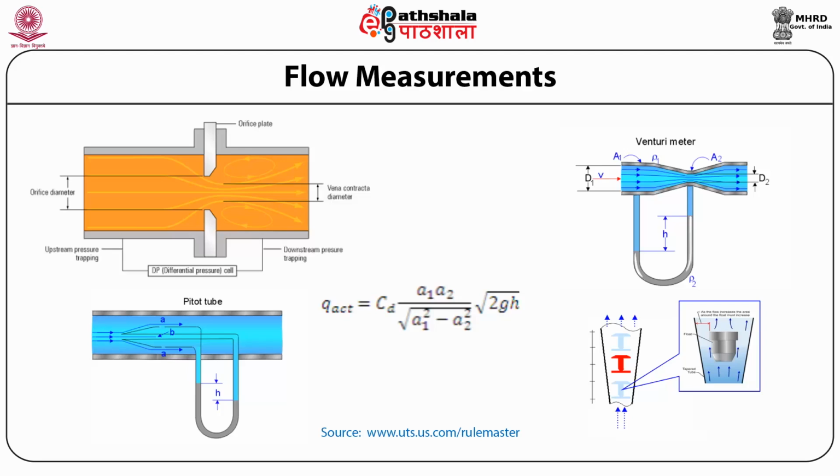That means the value of theoretical discharge and actual discharge differs significantly. In other words, coefficient of discharge is less compared to venturimeter. That is the reason why, for more precision measurement and large volume handling, venturimeter is mostly used. Of course, the design is difficult and hence cost is also high.